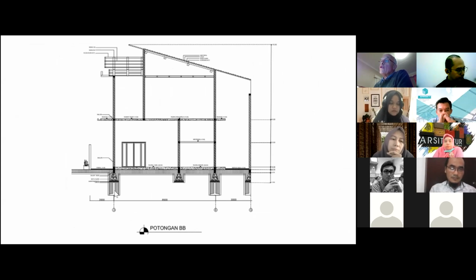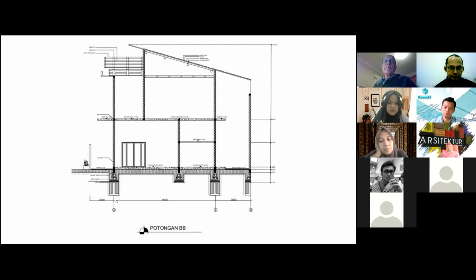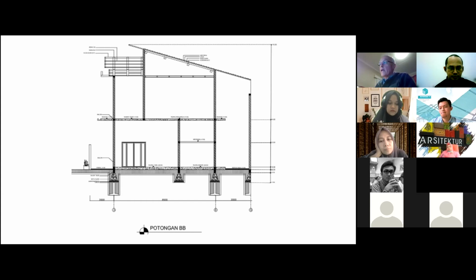But then the student has shown this square footing underneath. Now that is really a very silly suggestion. We would never do that, ever. We would choose to either have our foundations in reinforced concrete like that, or have our foundations as a stone construction like this. We would never mix these two types of construction. And so, the student has used a system that really is rather silly. But it's because of their lack of experience, I suppose.